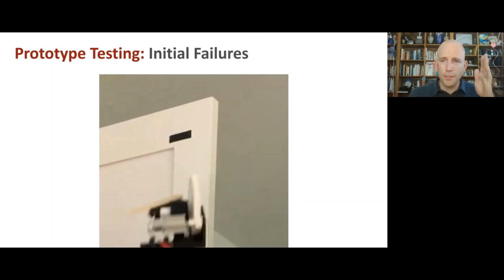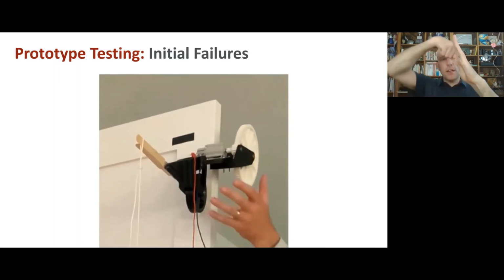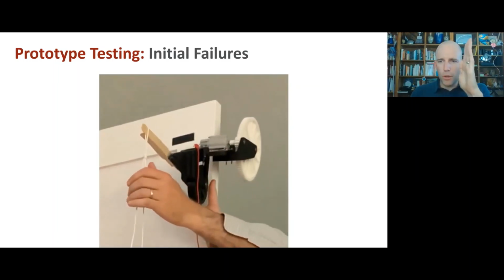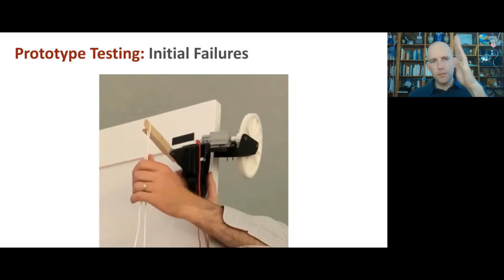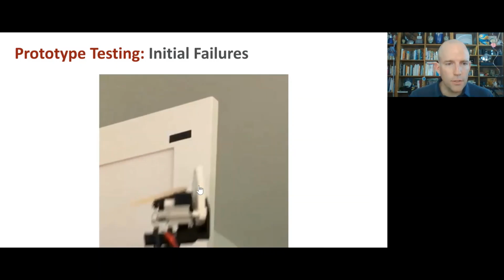Another issue that you can see here is as it rotates, or as heading changes, the payload force starts to have a horizontal component like we were talking about, and it starts to make this robot want to twist off. And you can see here, there's just a little popsicle stick hot glued on there as really a safety mechanism, emergency mechanism, so that when it starts to rotate, that contacts the door and keeps it from just falling off.